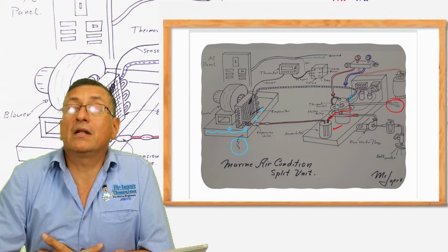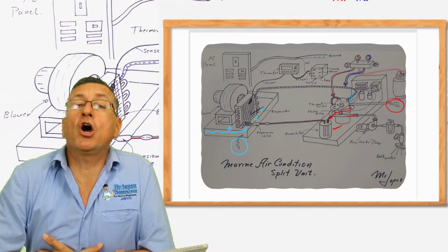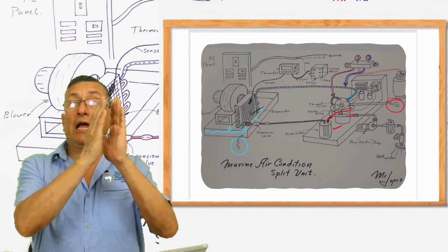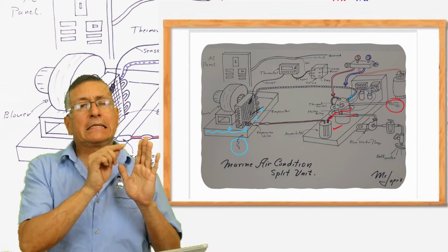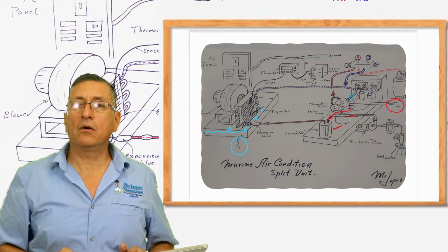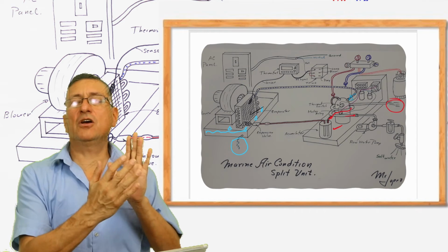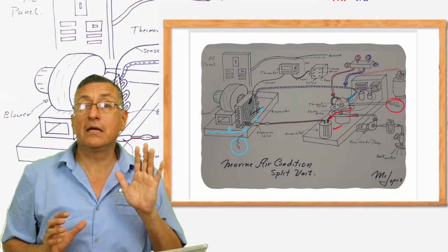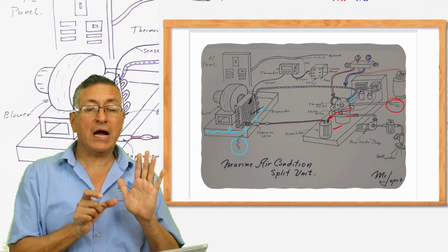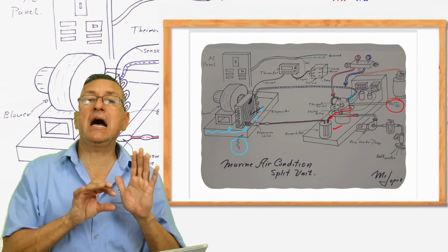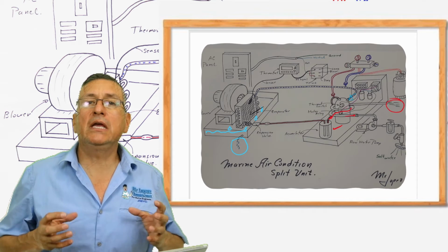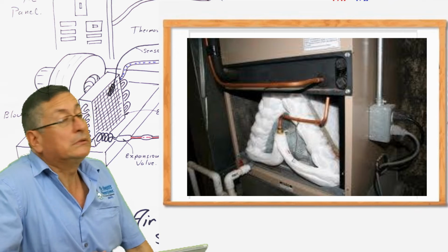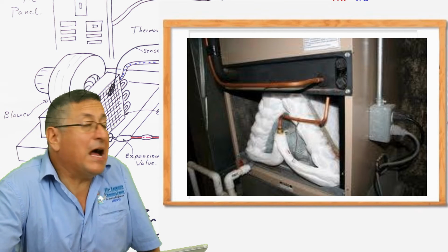Okay, if you don't replace that filter and the filter is clogged, and remember the coil of the evaporator, the pipes are practically frozen. What happens if the filter is clogged and less air than the recommended passes through the coils? What happened with those pipes? What happened with the ice around those pipes? Increase, and suddenly you have that situation. It's a block of ice.